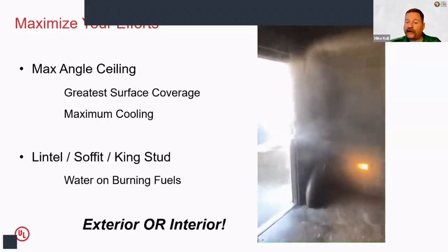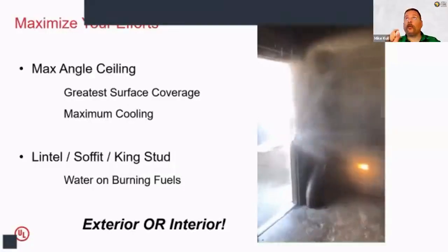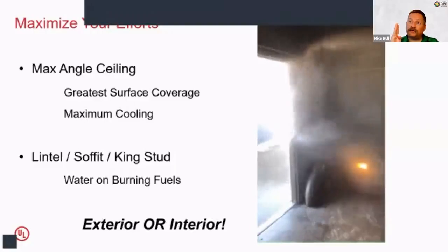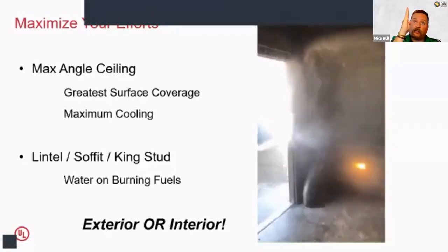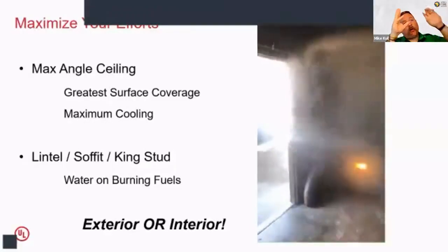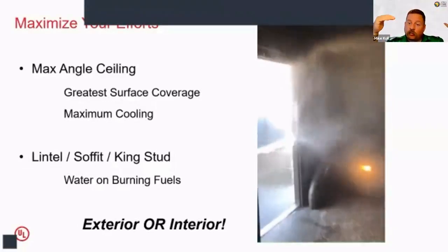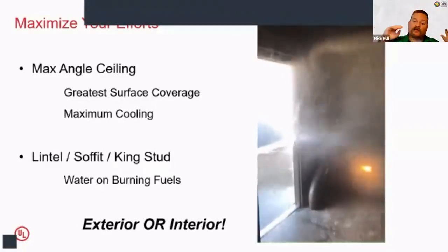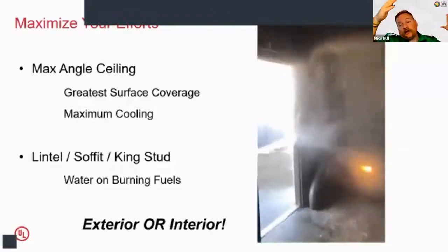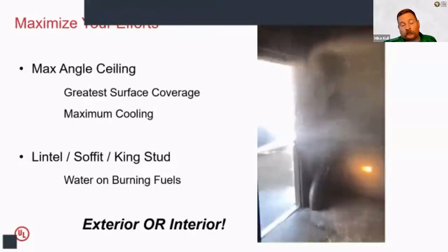Now, we're going to show you that in some videos later. But what happens is you're directing that water at a steep angle at the ceiling. That water is going to spread out and cover that 360 degrees, covering the entire ceiling until it hits the walls. When it hits the walls, the momentum of that water is going to run down those walls.